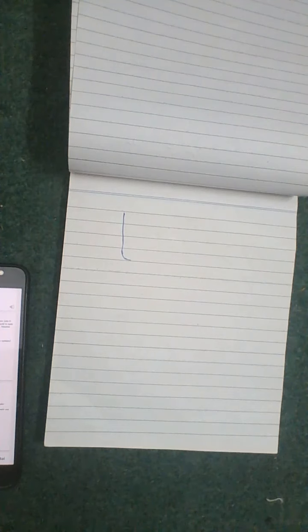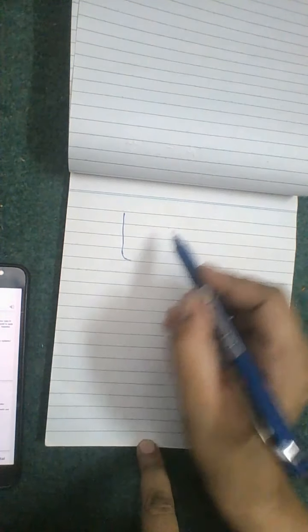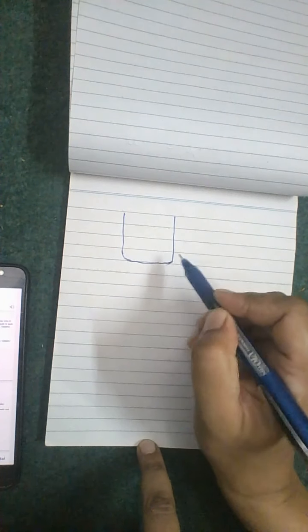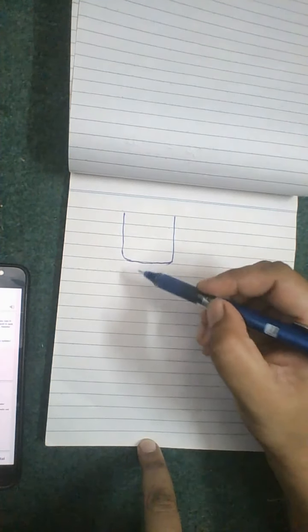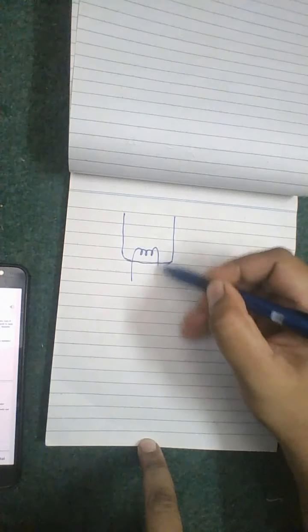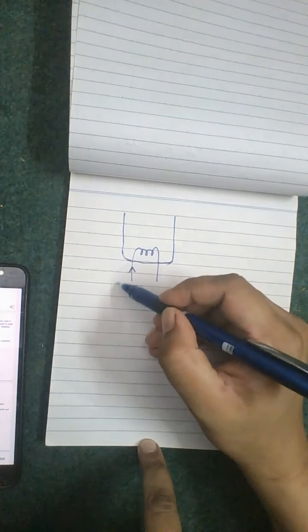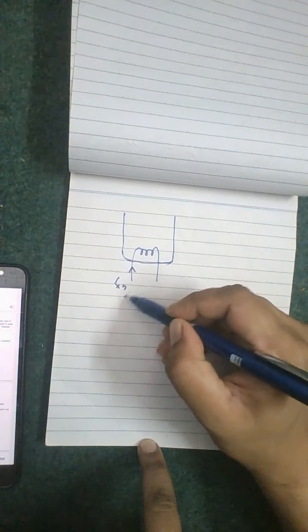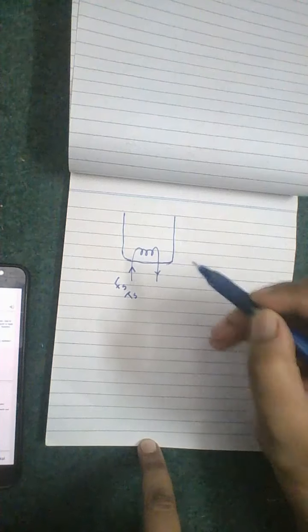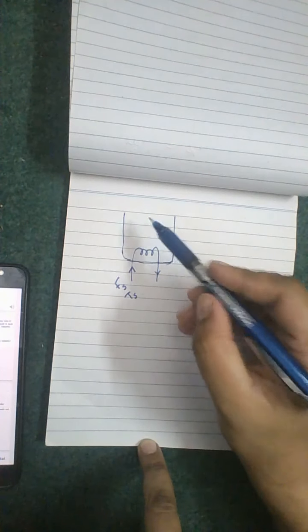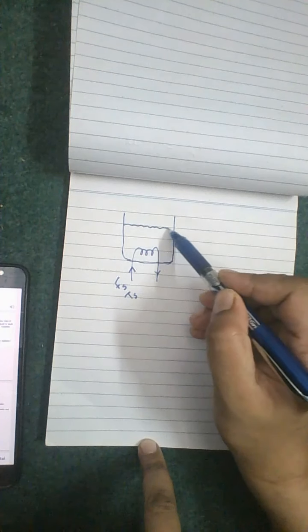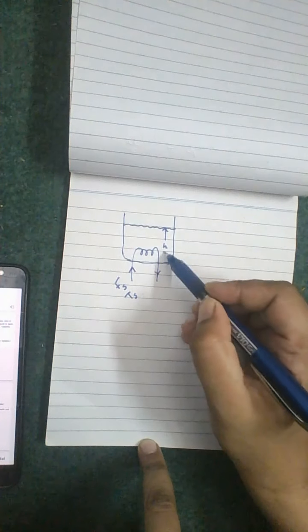In the previous lecture, we developed the basics of the mathematical models, on the basis of which we developed some mathematical models, or you can say the equations of the process. Let's do the first example. Consider the tank. This is the tank, and it has a heating system installed in it. This is the heater. The steam is entering from this side with a flow rate of Fs and temperature Ts, and leaving from this side. This tank is filled with liquid and a specific height is being maintained in it.